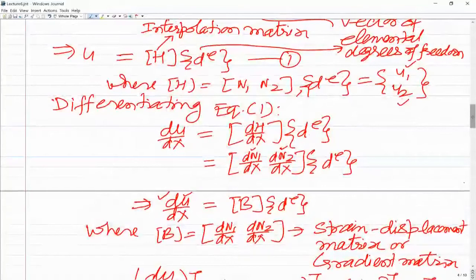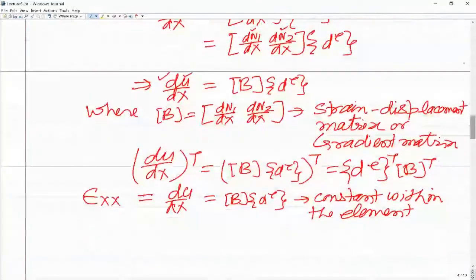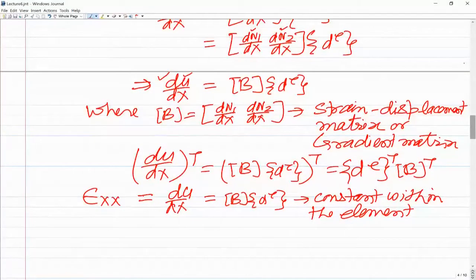One way is to use the Galerkin method and take the weight functions as w1 equal to N1 and w2 equal to N2, and then develop those two equations from the weak form. The other way is to substitute this approximate solution in the integral functional and minimize it. So we basically use Rayleigh's method to set up the equations for finding u1 and u2. I am going to use Rayleigh's method, based on the integral functional.